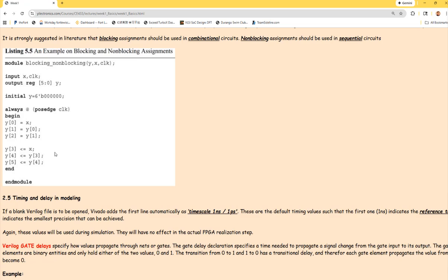And a lot of people, when they use FPGAs, they actually expect higher performance when they want to change to a new product, because they want to have their new ASIC design to be verified on the new hardware. So they would rather use a 28 nanometer technology launched 10 years ago instead of a 180 nanometer technology of the FPGA launched like 20 years ago. So FPGAs are being updated more often compared to microcontrollers.